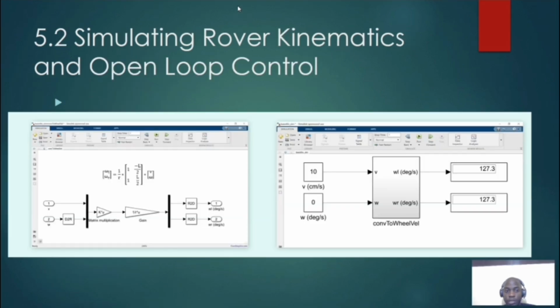Now we move on to our second part. At the lowest level of motion control is the differential drive kinematics. This is the mathematical model that translates the robot's desired overall movement, its forward speed, which we denoted as v, and its turning rate omega, into a specific speed requirement for the left and right wheels. The equations are quite simple. The linear velocity of the